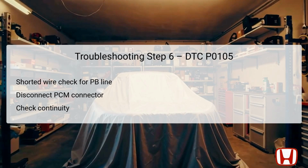Measure the continuity between the MAP sensor's terminal number 2 and body ground. If continuity is present, this indicates there is a short in the PB wire that needs repairing. Should continuity not be confirmed, it means the PB wire is intact and does not require repair.